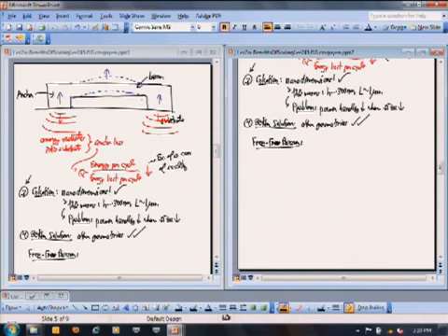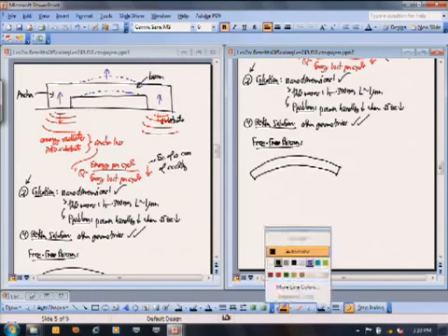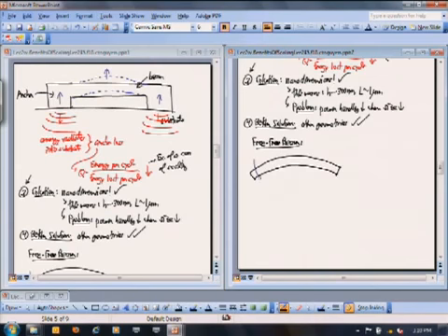Okay, but effectively in a free beam, you're going to get a beam to contort in resonance like this, where its ends you can see are moving quite a bit. Right? These ends are really moving. Okay? And this part here is also really moving up. So the ends are moving down, the middle's moving up. Well, there's going to be some locations right here and here where there is no transverse motion. Okay, so these are nodes.